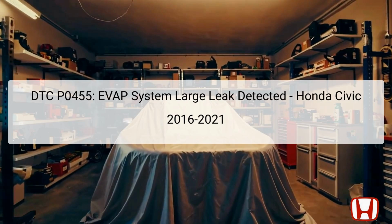Welcome to today's presentation on DTC P0455, which indicates that the EVAP, Evaporative Emission Control System, has detected a large leak. This error can also relate to DTC P0456 for very small leaks. The main components associated with this error include the EVAP canister, the purge valve, the vent shut valve, the fuel tank vapor recirculation tube, and the FTP, fuel tank pressure sensor.